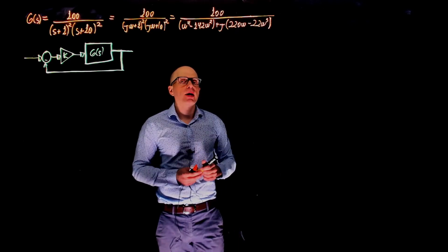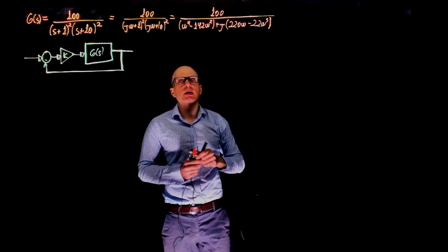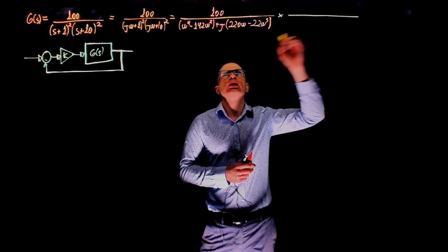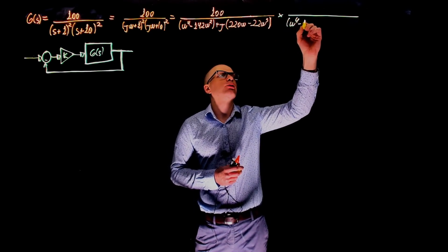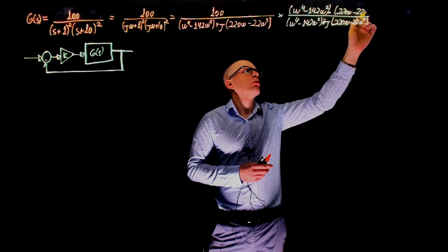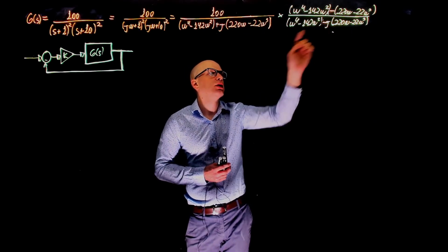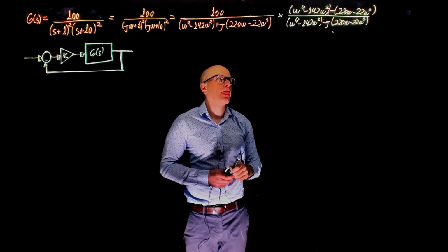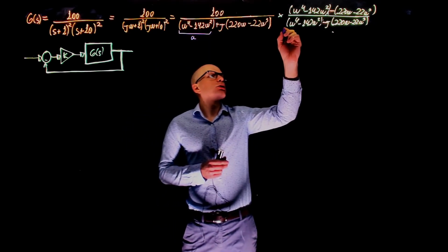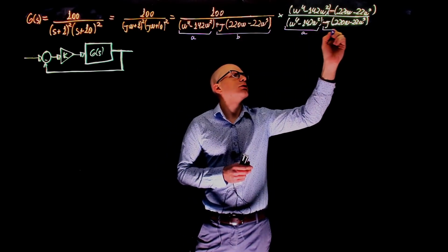So to find now the imaginary part of the transfer function, we need to get rid of this denominator that has a complex number. We can multiply the numerator and the denominator by the complex conjugate of the denominator, that is omega to the power of 3 minus all that. And here we have the transfer function multiplied by the complex conjugate of the denominator. You notice the negative sign change as opposed to positive. We can now clearly see that if this element here is called A, so is this one. If this element is called B, this entire element here is called -B.